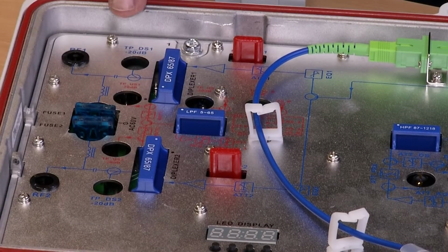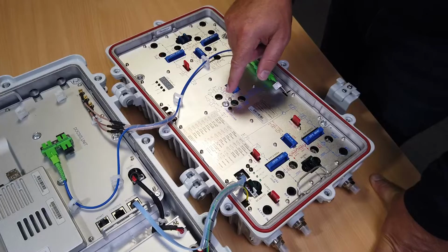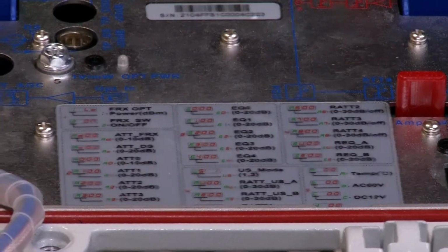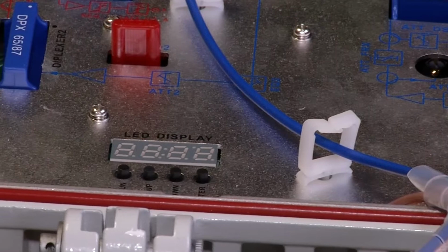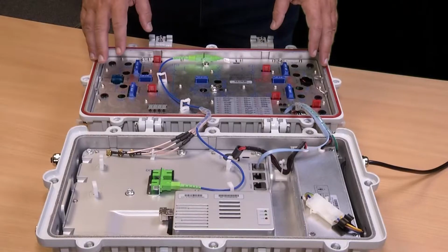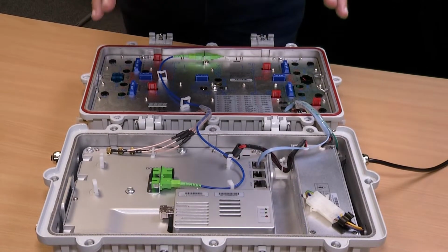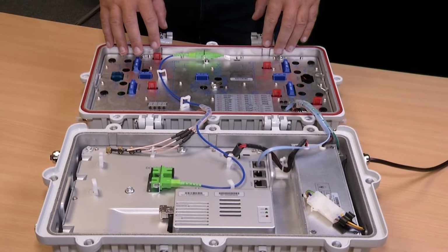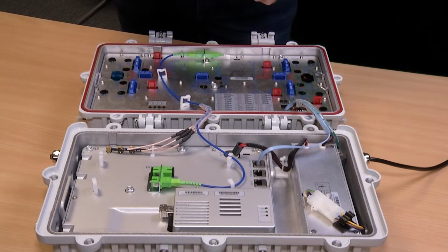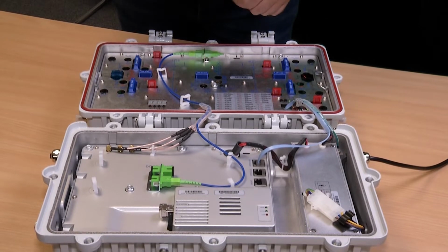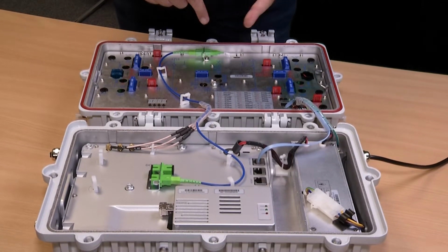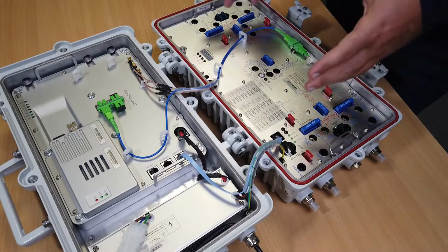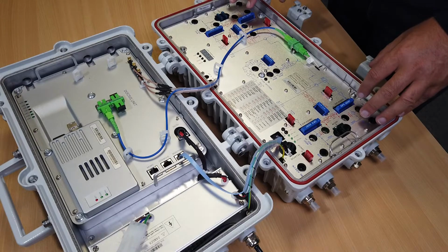Again, the test sockets. All settings that can be done at the fiber node are described here in the fiber node and can be configured here without equipment using the buttons. The important advantage of this FTTH fiber node is that it replaces an existing CMTS and fiber node pair. As a result, you don't need anything else at the head-end station or in the field. No advanced path or return path transmitters, and no CMTS anymore either. Everything is covered by this device.